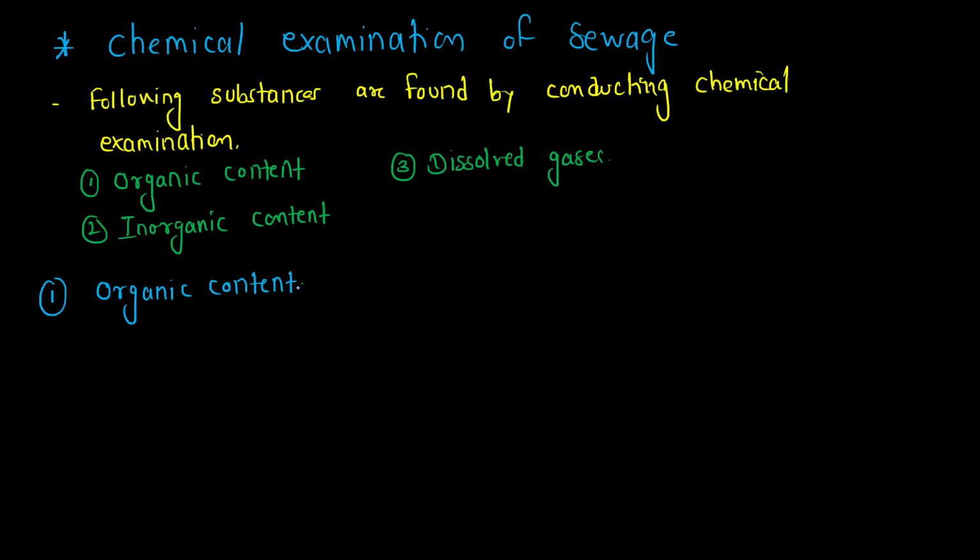Okay, so listen carefully now. The organic matter present in wastewater is a mixture of carbohydrates, proteins, fats and oils. Once again, the organic matter present in wastewater is a mixture of carbohydrates, proteins, fats. Now there is no straightforward method of testing the organic content of the wastewater. We don't have any method which can directly give the amount of organic matter present in the water. But we know that organic matter oxidizes by consuming oxygen.